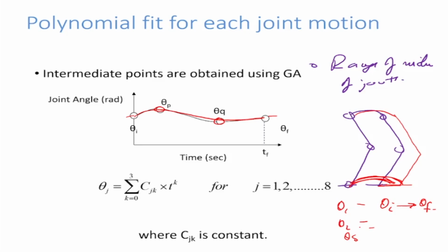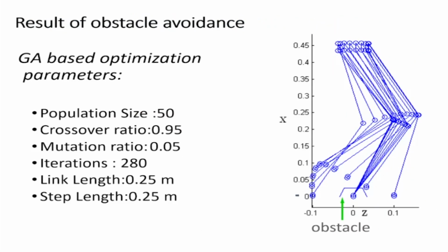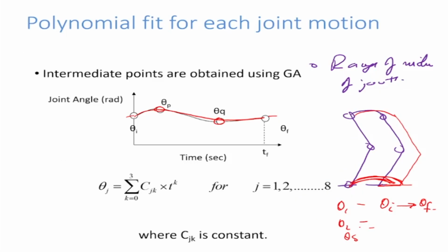Okay. Now you can use a genetic algorithm, which is easier to use because you don't have to do gradient based searches. So what the genetic algorithm is doing is putting different heights here, h1, h2, fitting a spline, dividing into 20 points, and for each of those points finding the energy and summing it up and saying this is the energy of the trajectory. By changing h1 and h2 randomly, it generates a very large number of trajectories, effectively giving you all kinds of trajectories, and then says this is the trajectory which is the minimum one.